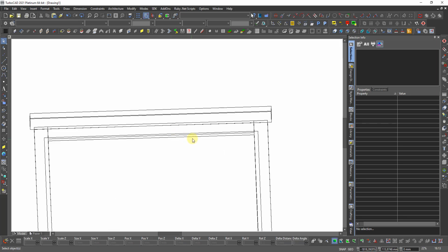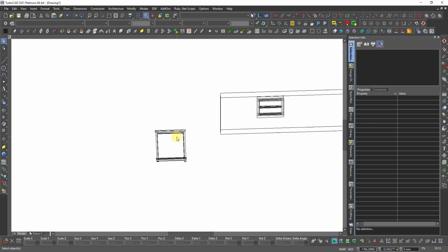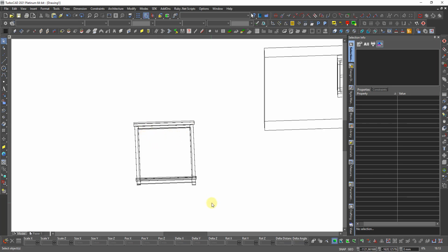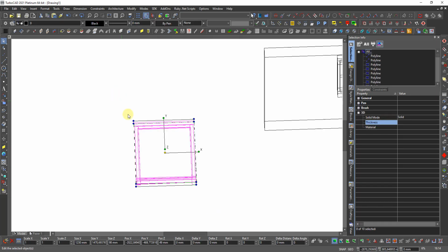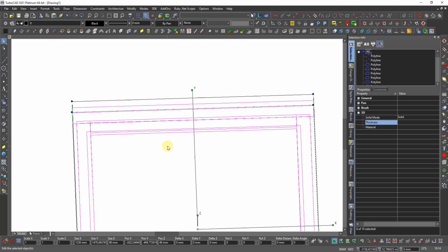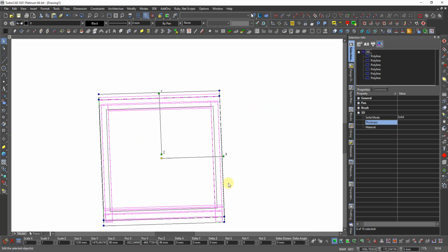It would be nicer if I had the 2 polylines in red, but okay, too late now. I select this, and then I try to unselect. At least that polyline is easy, and then I should have that polyline. That was the 2D part line. Then I should explode them all, because with the polyline this thing will not work. I use the explode tool.